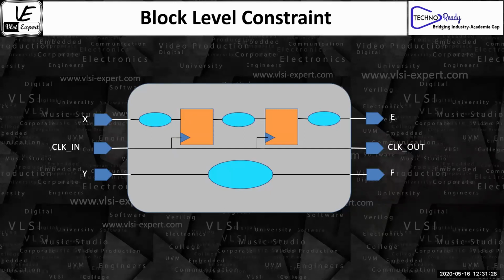The way digital logic usually works is you are given one clock cycle. From rising edge of the clock to the rising edge of the clock, you are supposed to do one operation or combination of operations. So you get some input here at X, you do an operation in this blue cloud, and when the rising edge of the clock happens, you're supposed to capture it in that first flip-flop. So this is the first part.